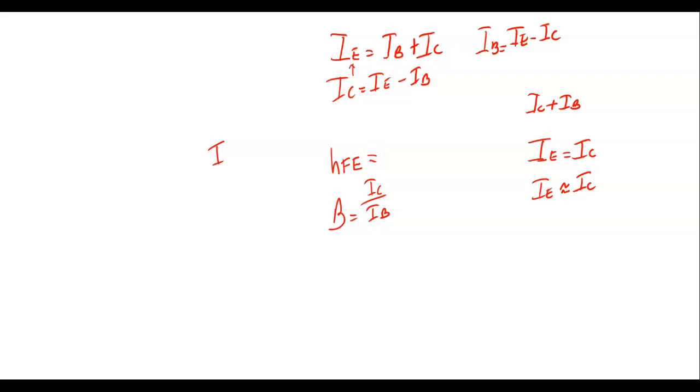The problem we have is that our math is exact, right? You understand? But our components are not. So there's very seldom that you'll ever calculate where you'll come up with exactly what you measure, unless you measure all your components. So back in DC, what did you do? You measured all your resistors, right? So when you did your math, you didn't use the color-coded value, you used the measured value. So that means your calculations and your answers should have been really, really close. But now we're not going to do that, right? Because we know that we have all these tolerances.